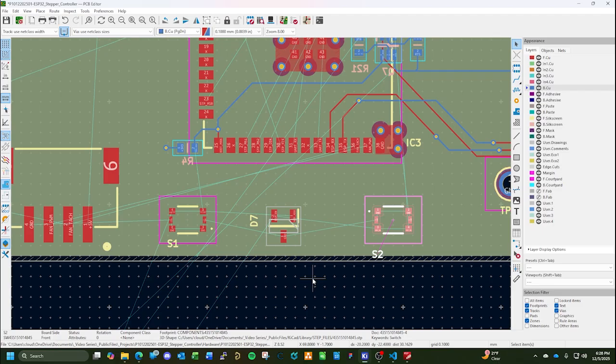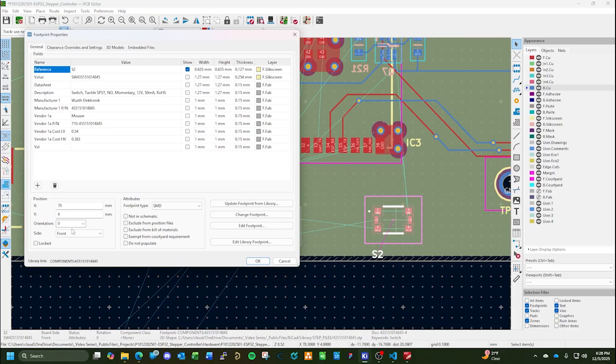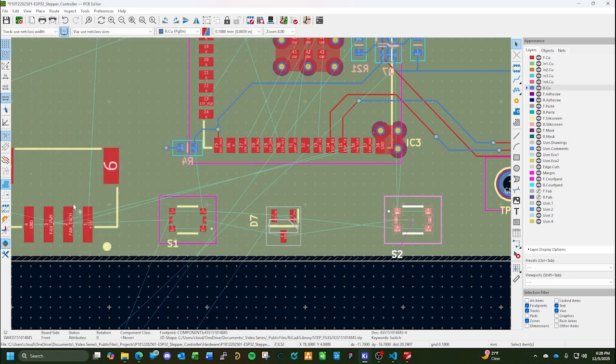Because they're not very large push buttons. And if you're trying to fumble and do your boot and your mode, if you've got a program issue with the USB or whatever, it's not communicating or programming properly, trying to fumble with these buttons when they're too close together is a pain in the rear. So if you've got the room, space them out. We're just going to go ahead and move them to 80. Give yourself the room. Don't give yourself the headache. I learned the hard way.